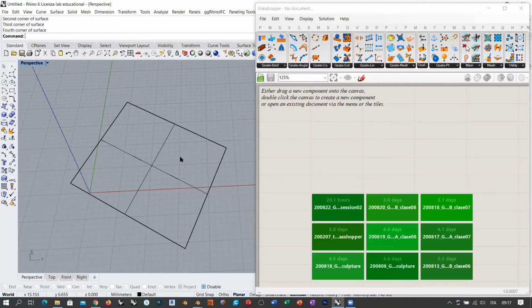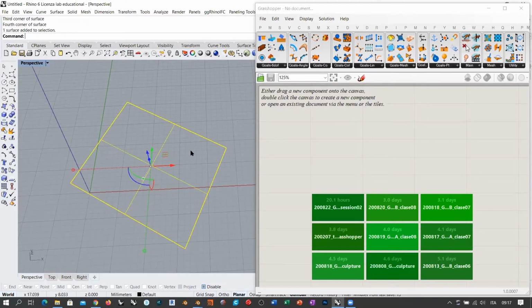And you cannot ask a computer to perform infinite calculation because it will take infinite time. And we want calculation to happen in a finite time. So that's why in all calculations based on some geometry, there is always some discretization going on. And this operation in Rhino Grasshopper means converting surfaces into meshes. So as Kangaroo is basically a physics simulation software, you must come up with a discrete system. You cannot work with smooth and continuous surfaces.